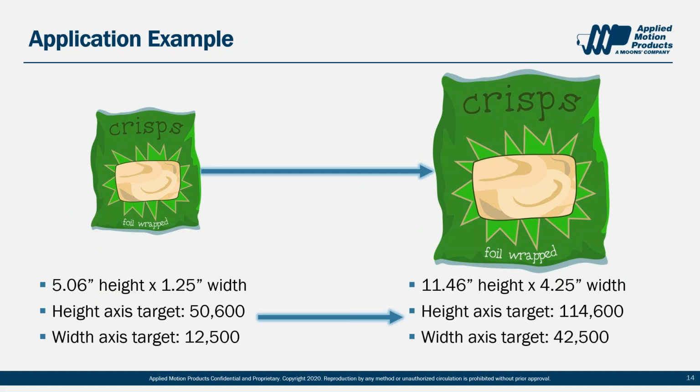Now again, none of this electronic gearing stuff is unique to the TruCount encoder. It applies to all Applied Motion Products drives. The real advantage of the TruCount comes in how absolute positioning ties in with the electronic gearing. But to make that work, you also need to tell the motor where to start measuring from. So let's start to look at that with homing.